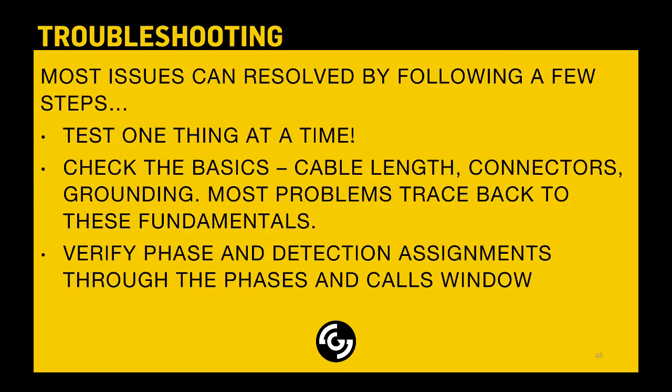Next thing is just always check the basics, right? You've got your cable tester, test the cable length, make sure that it is 300 feet or less, either between the camera and the processor, or the processor and the repeater, and then the repeater to the camera. So test each line individually and validate that you are within the specification of 300 feet.